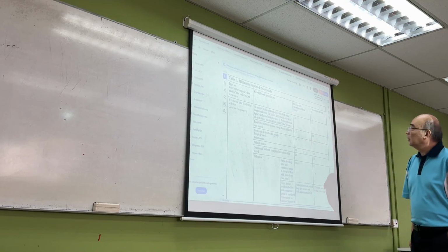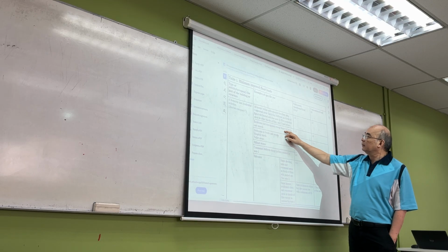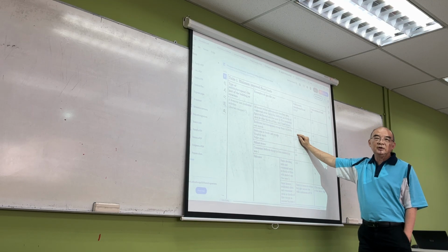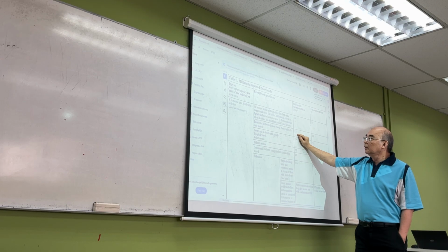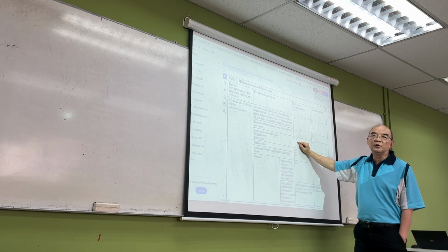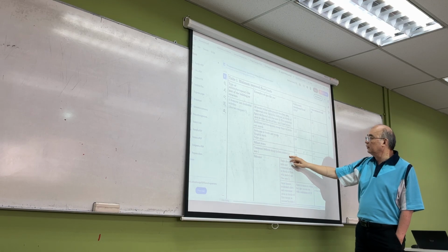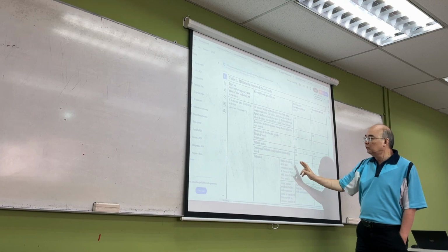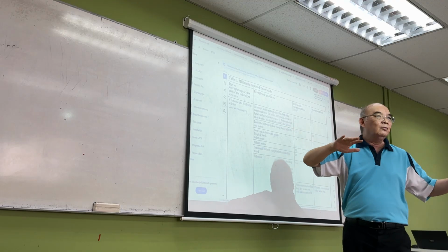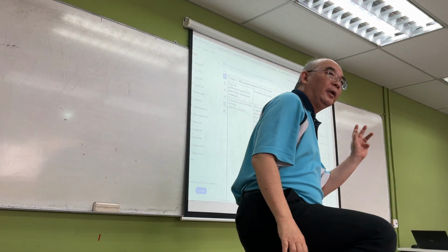So, for example, bedrooms and dormitories, except those in hotels and motels, are 1.5 kilonewton per meter square. Bedrooms in hotels and motels or hospital wards, and toilet areas, are 2.0. Billiard rooms 2.0. Communal kitchens except in flats 3.0. Balcony 1.5. So different areas have different loading. Okay, so this is a British code.